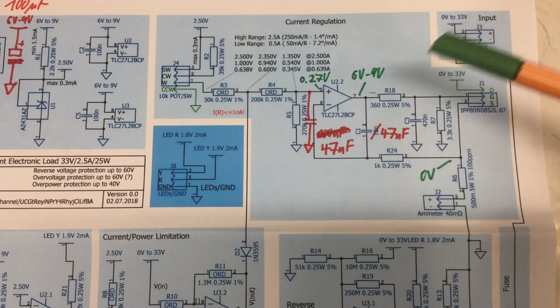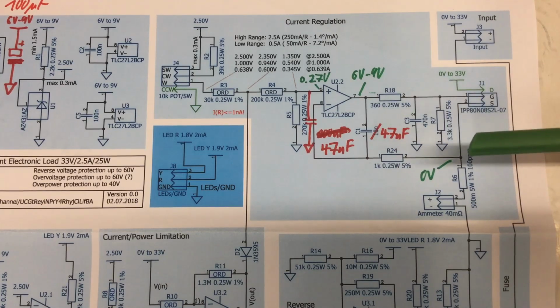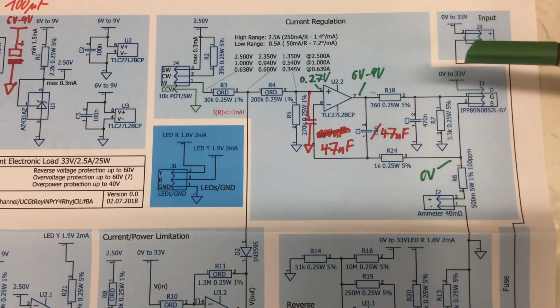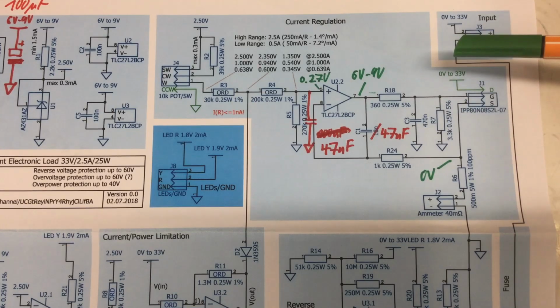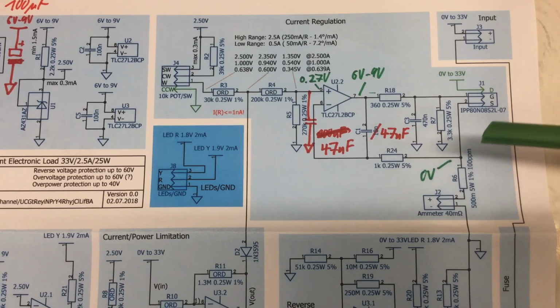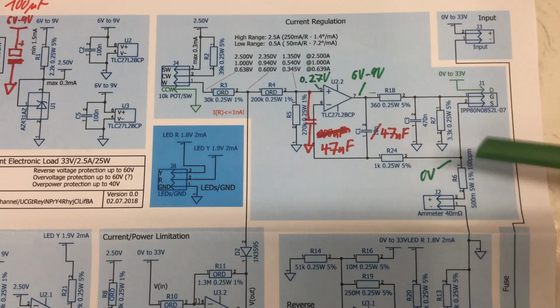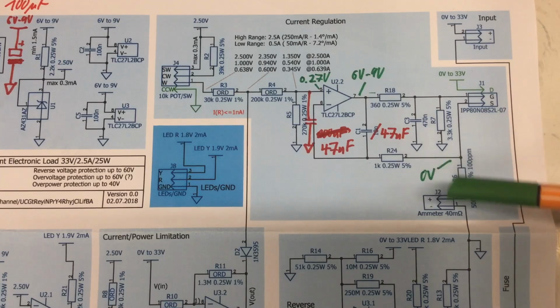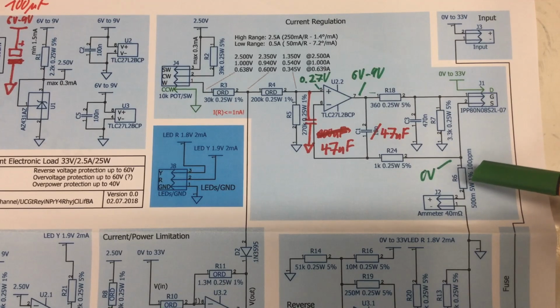I'll show you what I changed. I thought about a lot of possibilities to dampen that big transient. Our MOSFET, remember, is completely open, and suddenly current shoots through here, and we have a big voltage drop here. You could make a really big capacitor around here, which would otherwise influence the behavior of that circuit for low currents very negatively.